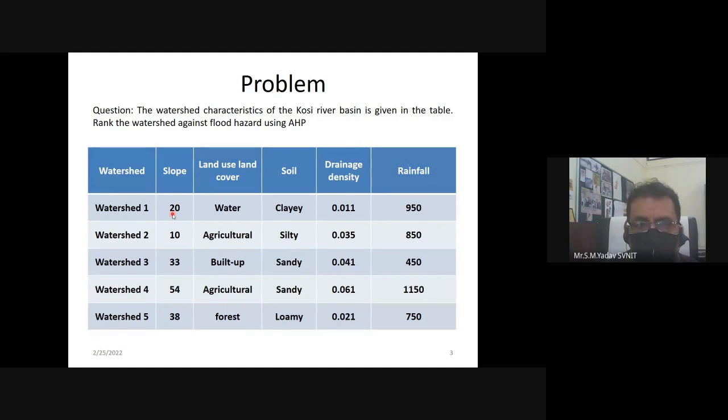So if you want to apply this, and if you want to use these parameters for indexing any city, town, taluka, place, village, etc., you have to have that data for the basic parameters, right? The parameters I am considering here are for finding out flood hazard, exposure, vulnerability. Exposure means how much that particular area is exposed to flood, right? And collecting this data for watersheds 1, 2, 3, 4, and 5, I will be doing indexing using fuzzy logic, right? So that is our objective.